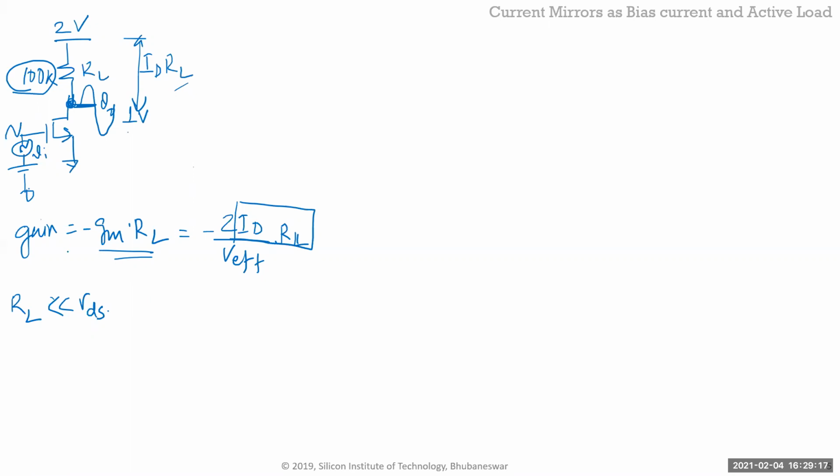Somebody gives me a power budget and says, whatever you do, your current should be 100 microamps here. And this is 1 volt here, right? If that's 1 volt, then I don't have anything to do with RL. The RL has to be what? This is 1 volt and this is 100 microamp.